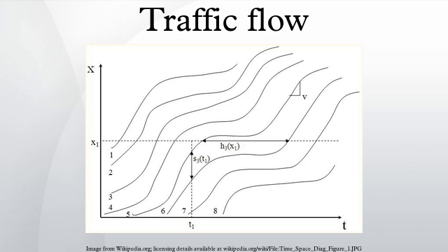average speed measurements obtained from this method are not accurate because instantaneous speeds averaged among several vehicles does not account for the difference in travel time for the vehicles that are traveling at different speeds over the same distance, where m represents the number of vehicles passing the fixed point. Space mean speed is the speed measured by taking the whole roadway segment into account. Consecutive pictures or video of a roadway segment track the speed of individual vehicles, and then the average speed is calculated.